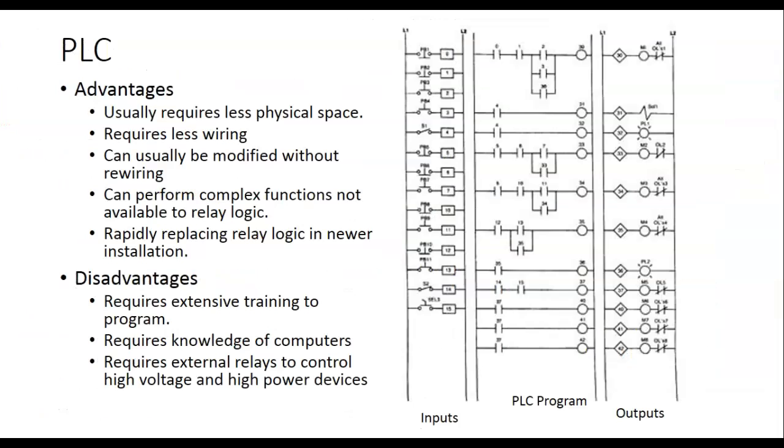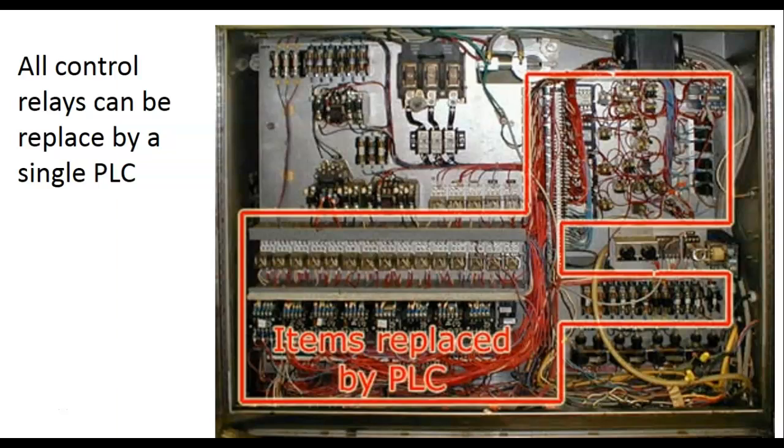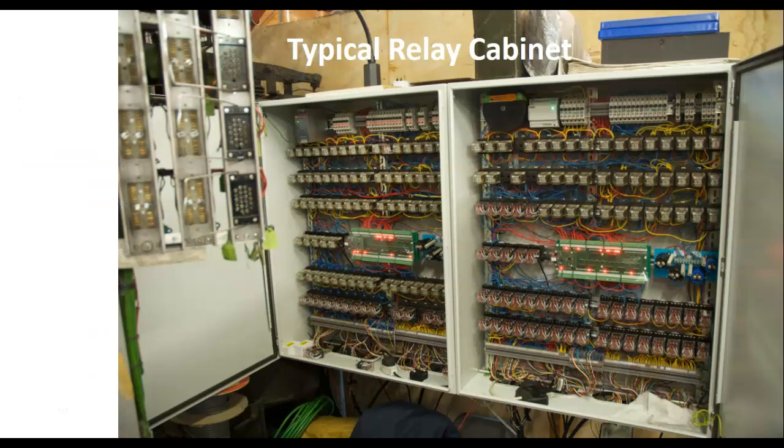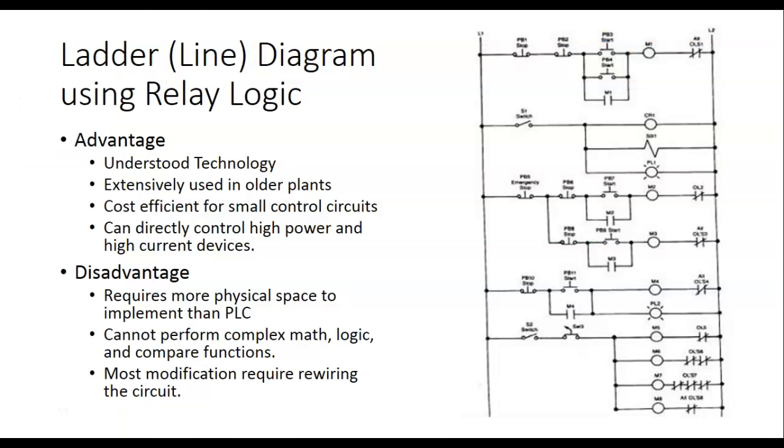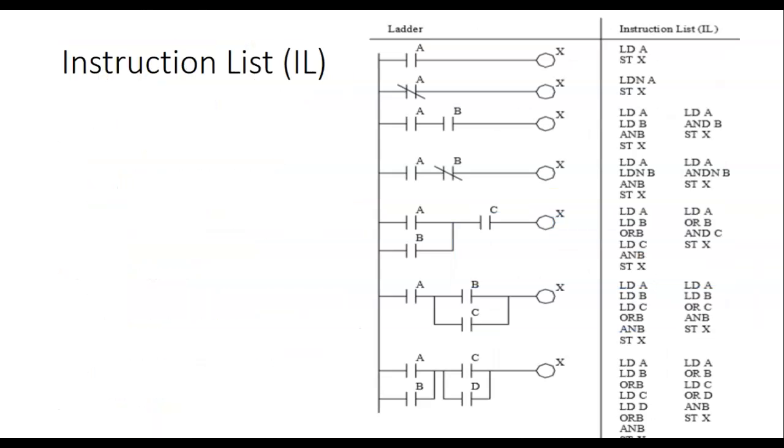You know, we looked at a little programming, and what I wanted to show y'all is once you learn how to program these things, it's not that complicated. What we're doing, we could do the same thing with relays, but I would have to run all those wires. And what's nice here is that when you hook up inputs, all your inputs hook up exactly the same. So I would come over here and I would have a common. And then I would come over here, and of course we're running sinking inputs.